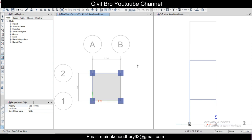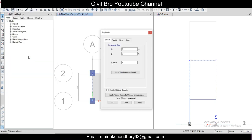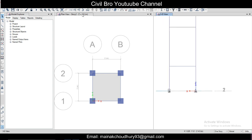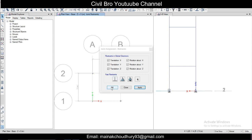After that we can go back to the front view, click on escape, select this and go to edit, and OK, select this and select this also, and then go to edit, go to replicate and story 3, apply. So once this application is done, we can simply go to the base story here, select this and assign joint restraints, select on the fixed and OK.